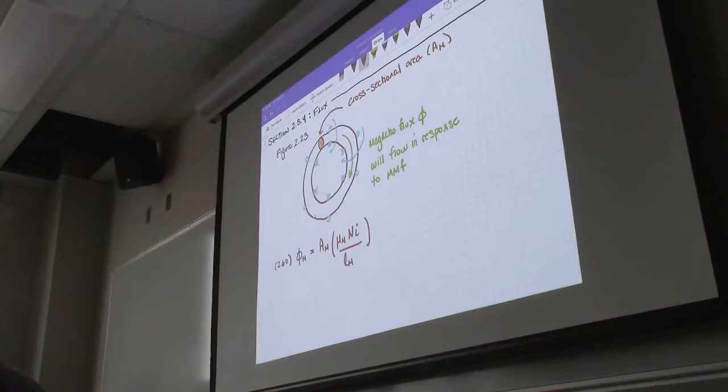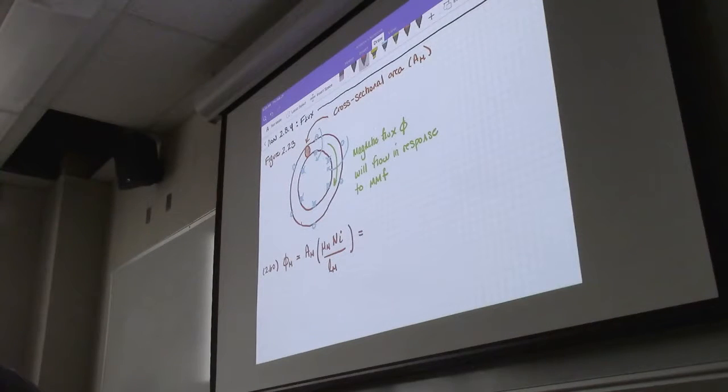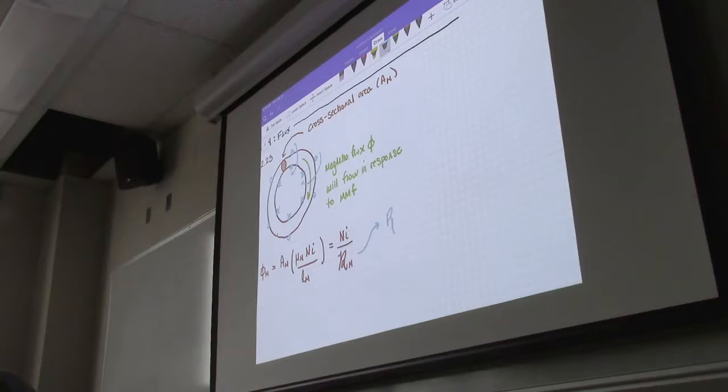This is also equal to another version, or shifting of the elements. We can also say this is equal to N times I divided by the reluctance, where the reluctance is then equal to the mean length over the permeability of the ferromagnetic material times the cross-sectional area.